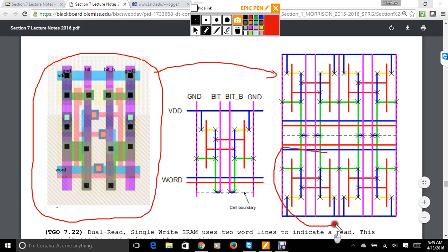And then in this layout optimization, see how we have the pull up and pull down networks. You see how they're flipped. If you compare these two cells, the pull up network is here and the pull up network is here. I described that. You couldn't do this the other way, and you'd have to make it longer, which would increase your wires and increase your timing delays. By flipping it that way, it's the same amount of area. However, by reducing the wire length, you're ultimately reducing your power consumption and your interference.